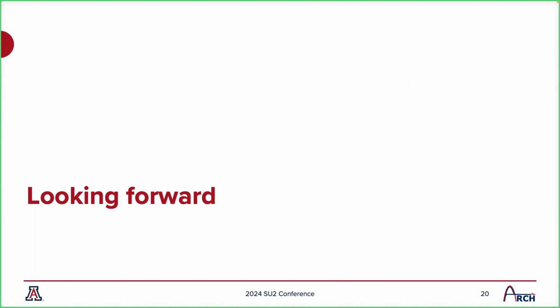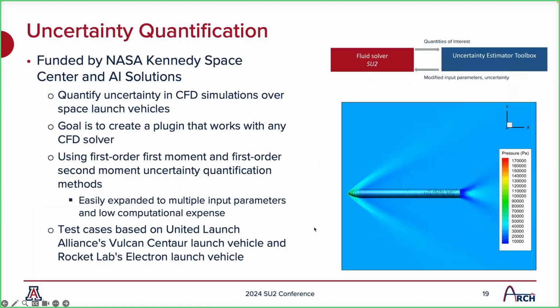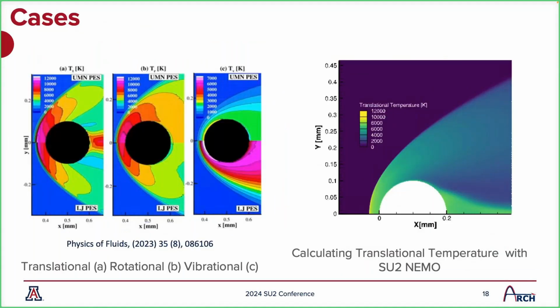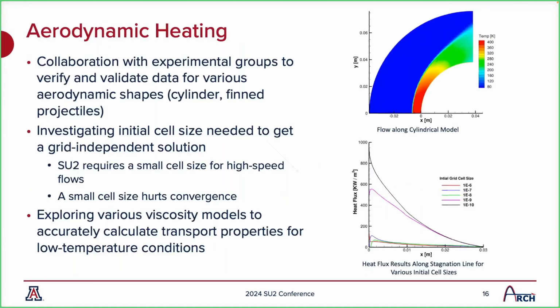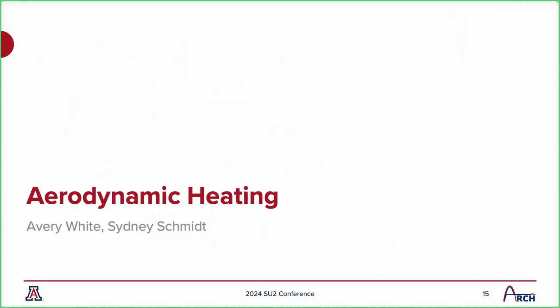Yeah, that's right. If I can find the slide, and there's a little lag. For these leading edges on hypersonic vehicles, you need a sharp leading edge to reduce the drag. But a sharp leading edge results in very high heat loads. So one of the things we've been looking at is a low work function material at leading edges, and essentially we convert that heat to electricity. When you do that, you're emitting electrons into the flow field.